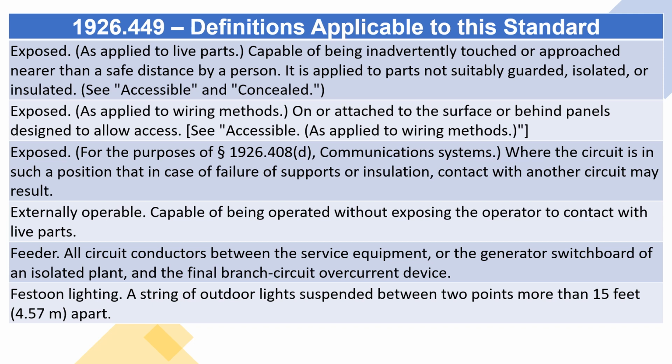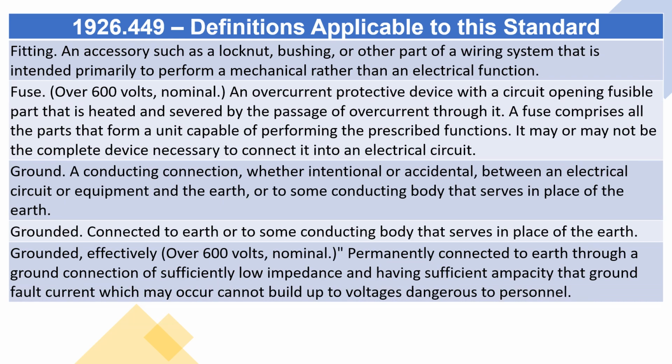Feeder. All circuit conductors between the service equipment or the generator switchboard of an isolated plant and the final branch circuit overcurrent device. Festoon lighting. A string of outdoor lights suspended between 2 points more than 15 feet (4.57 meters) apart. Fitting. An accessory such as a lock nut, bushing, or other part of a wiring system that is intended primarily to perform a mechanical rather than an electrical function.